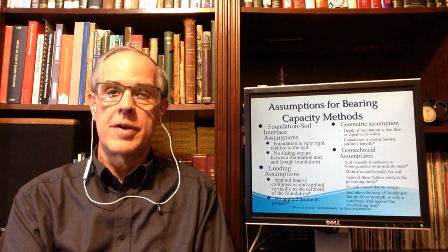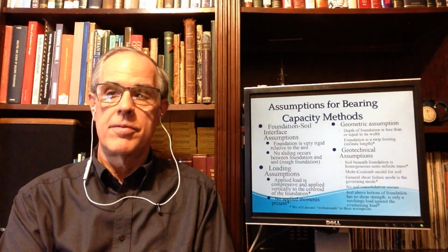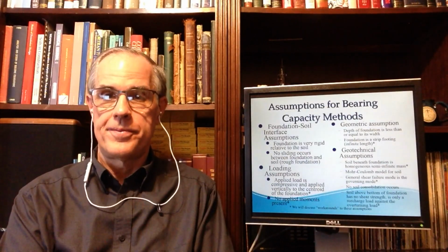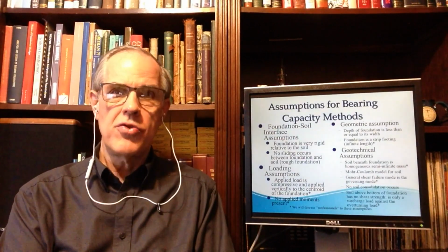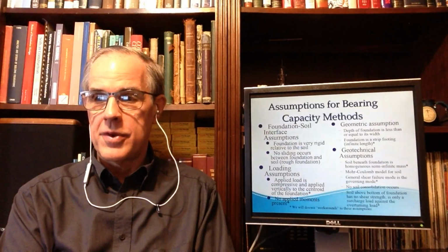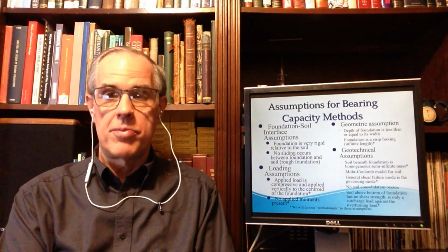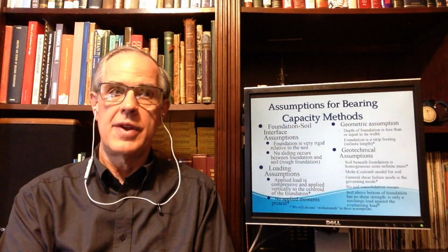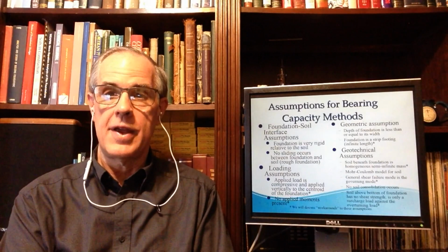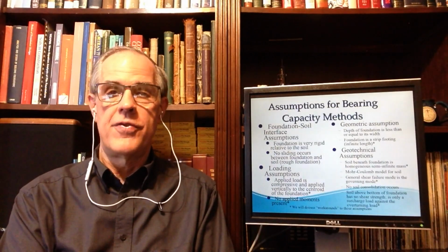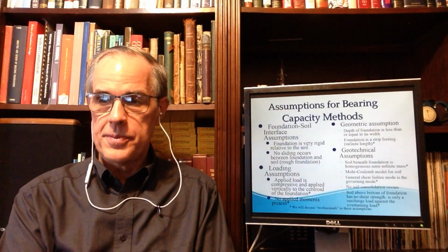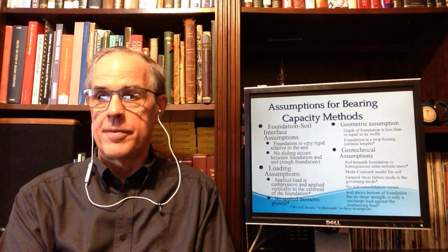The foundation is very rigid. We talked about rigid versus flexible foundations. No sliding occurs between the foundation and the soil. It's a rough foundation, and usually most construction crews will gladly oblige you with that. Loading assumption: the applied load is compressive, without tension. These foundations do not carry tension loads, and that has some important implications. The load is vertical, and it is applied at the centroid. There are no applied moments present.